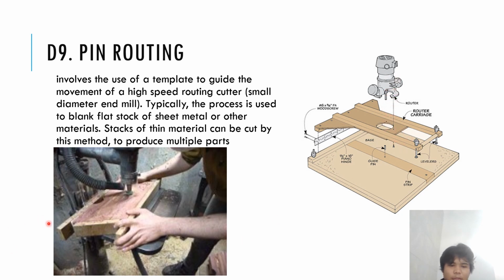So I have a video here. I'm set up today to route the dishes and trays for the Dinner for 10 collaborative project. This is one I did a couple days ago. This is one of the end trays made out of cherry. I cut the parallelogram on the table saw, drilled the cove in the corners with a 3-inch hole saw on a jig in the drill press, burnt my little logo into the back,